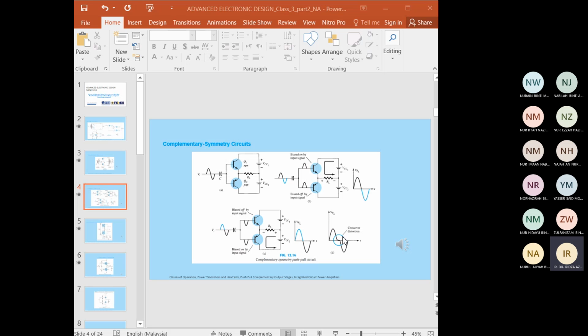So the result is from the condition that the circuit does not give exact switching of one transistor off and the other at the zero voltage condition. So both transistors may be partially off, so that the output voltage does not follow the input around the zero voltage condition. So biasing the transistors in the class AB will improve this.